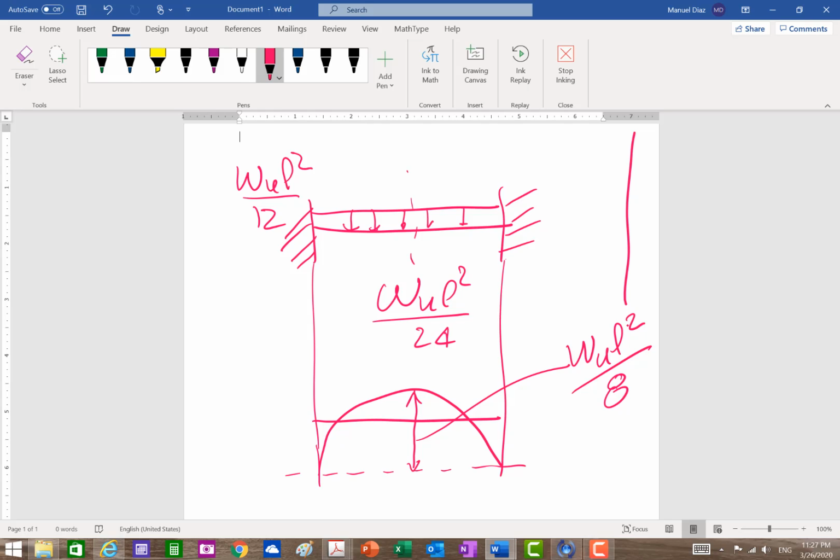Well, so this beam develops that. So then comes the concept of plastic hinge. Now, in analysis you'll probably learn about your hinge, right? Where the moment is 0. Well, that's different. That's an actual hinge where you cannot develop moments. A plastic hinge, you actually develop moments. Okay?